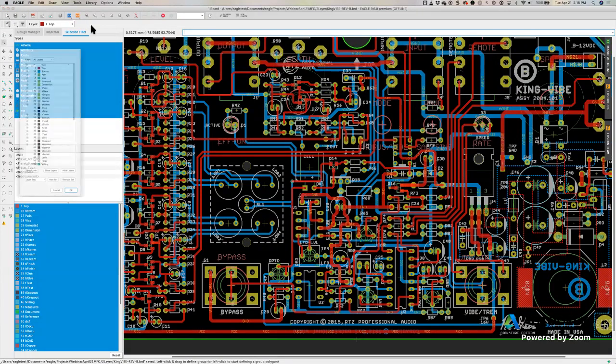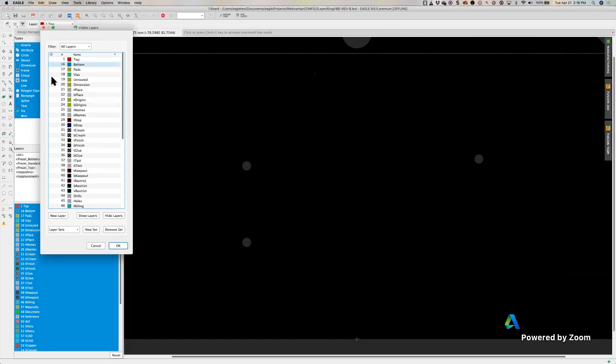So my top copper, what my board is going to look like on the top copper when I send this to the board house, is like this. This is my top copper layer, and that's my first clad. Then I'm going to generate another Gerber file. Actually,